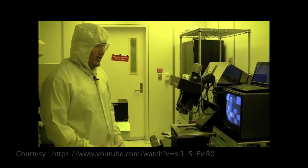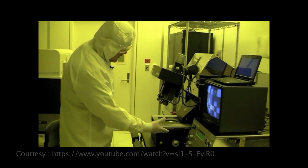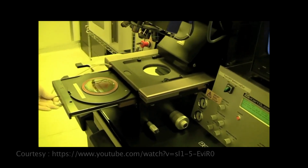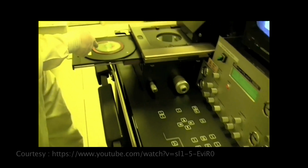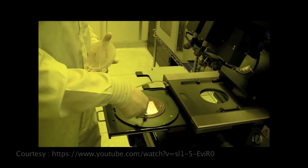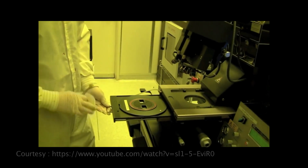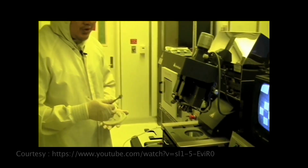So after exposure, you need to unload your wafer. What you do is you come to the screen, and it will say pull slide or unload exposed substrate. So you just pull it out, and then you press the enter button, and then the vacuum will be released. And you can take your wafer out. And then you put it back in. So that's how you unload your wafer after exposure.